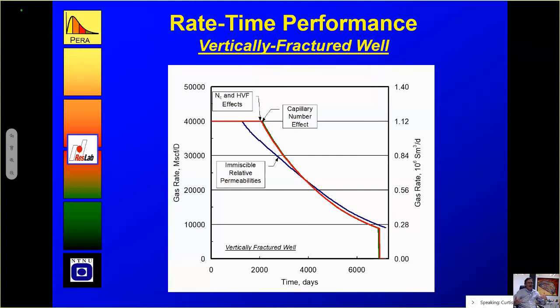That's the effect. It's not the time it takes to reach steady state or something. But I think this assumes a more or less ideal fracture, whereas in reality we see that most of the fracture is damaged. And there have been a lot of papers now published by a consortium for hydraulic fracture in the US. And they see that the pressure drop is not really linear within the fracture and is also taking the shape of due to damage which happens in the hydraulic fracture. It takes a more exponential flow.